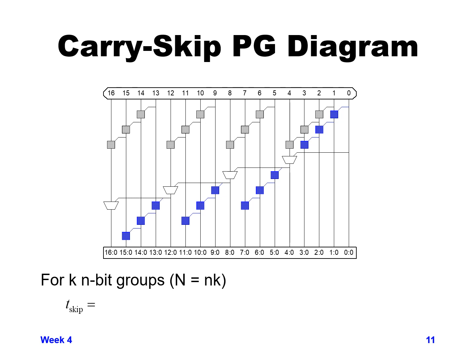So the total time delay through our carry skip adder is similar to what it was for the ripple adder, where at the very beginning we have 1 delay going through our initial propagate and generate for each individual bit. At the very end we'll have a XOR function that we need to do for the final sum, which in this case is up at bit 15, and then in between we have an AND OR function that we need to do,